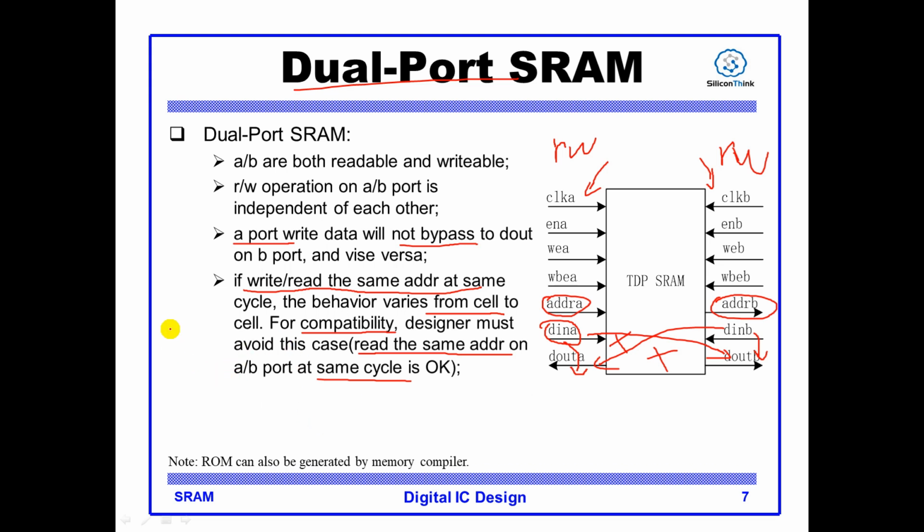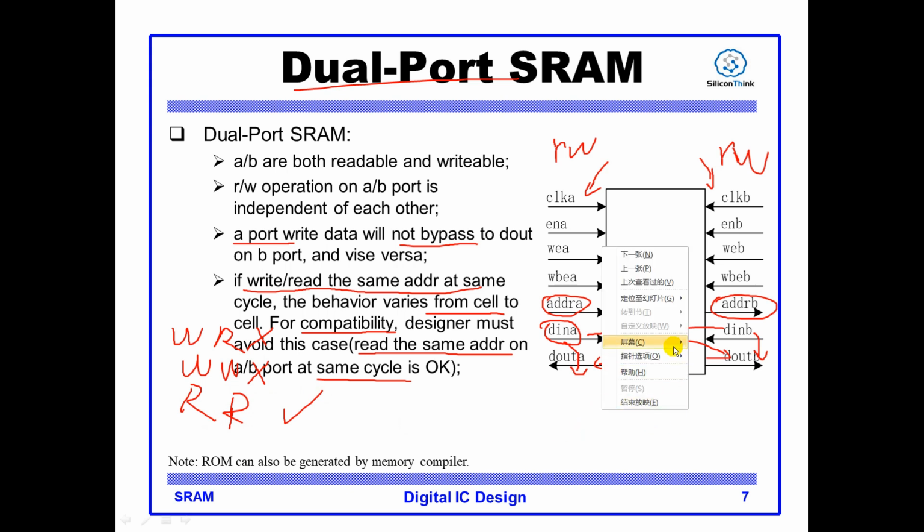But if there is one write, one read for the same address in the same cycle, this is not allowed. And two write on the same address of same cycle, this is also not allowed. Okay. This is allowed on the same address.